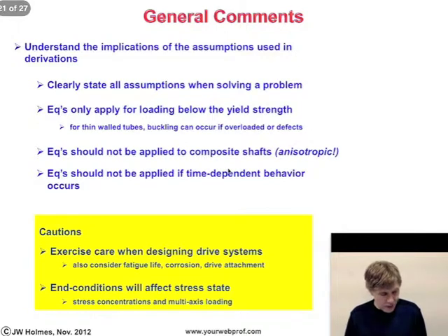All right, and a few cautions. I've been a designer for quite a few years, and many of you are certainly interested in design, or you wouldn't be taking these courses. Exercise care when designing drive systems. Also, consider fatigue life. What are the implications of cyclic loading of a shaft? What about environmental effects such as corrosion? So you have to be careful when you select the material that you don't have corrosion effects.